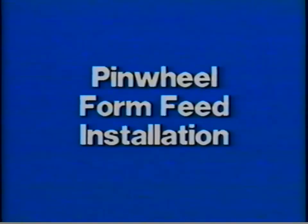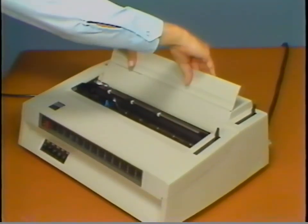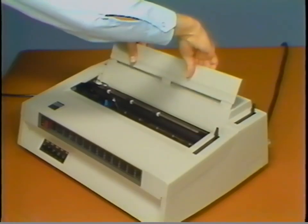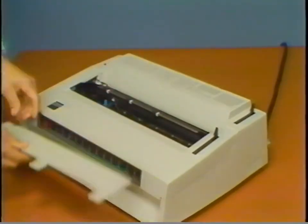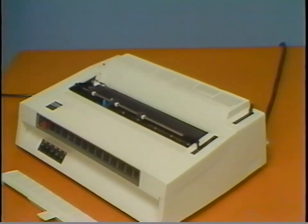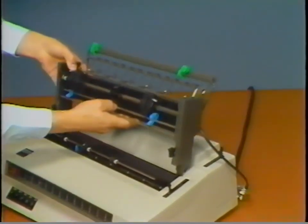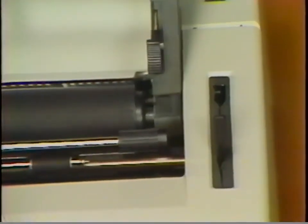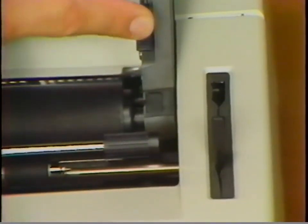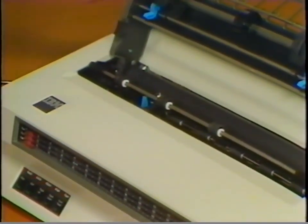The pinwheel form feeder is an optional feature which is installed by the operator. To install the form feeder, first remove the paper table and pull the paper bale forward. Then place the latches over the platen shaft. The right bracket fits over this gear on the platen shaft. Rest the form feeder on the rear cover, then push the latches to the locked position.